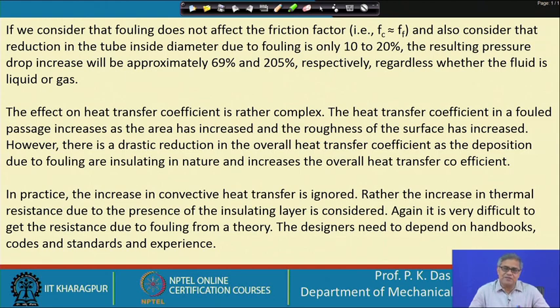So, there are many aspects of fouling. First thing, at the design stage I have to take some sort of precaution so that fouling does not take place in a rampant way, and precaution so that my design is to some extent oversized, so that even with fouling I am capable of having the plant performance I have aimed for.